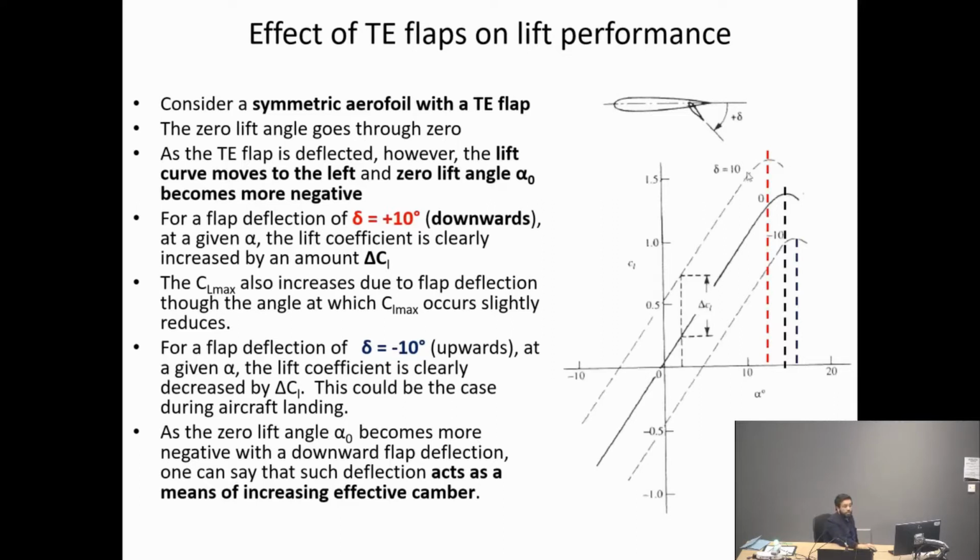So you get higher lift, but the stall angle, as I'm showing hopefully with the dashed lines, here let's say is 13 maybe using the flaps, but for the main wing it is actually higher at 15. So the trailing edge flap gave you more lift, but it reduces your ability for extended stall. The stall angle actually becomes lower, so you have to be very careful how you operate these things, of course. There is a slight decrease in the stall angle.